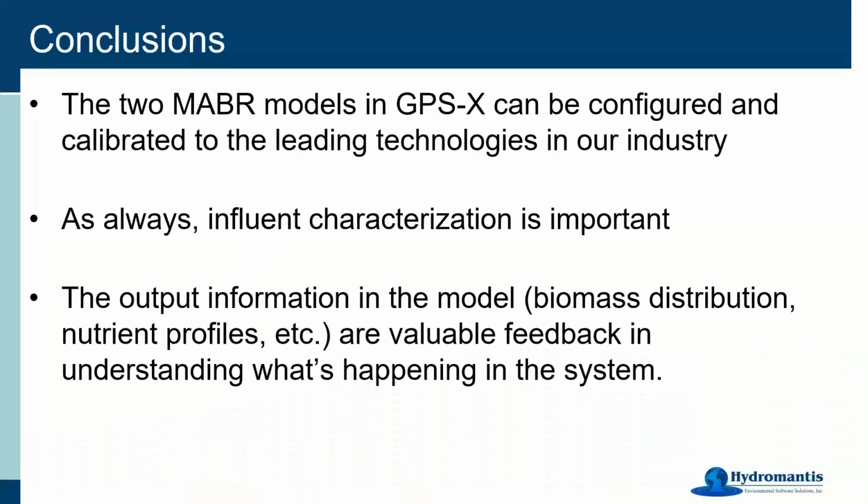Okay, so just to conclude, we have those two MABR units in GPSX, the hollow fiber and the flat sheet. And they can be configured and calibrated to those types of leading technologies that I mentioned earlier. I have seen all three of them successfully calibrated using our model.